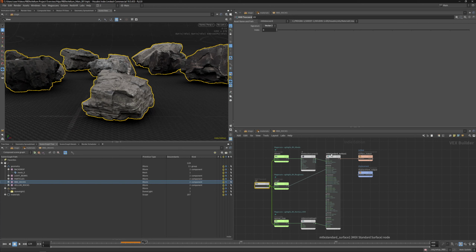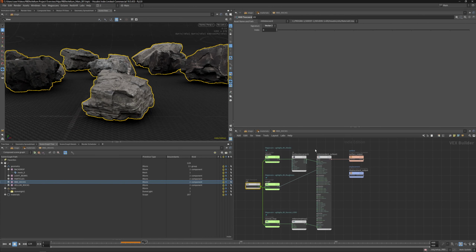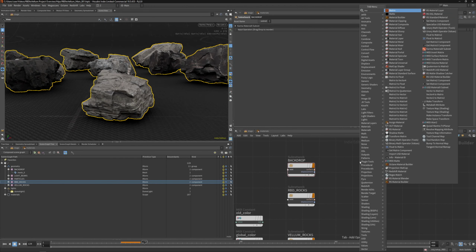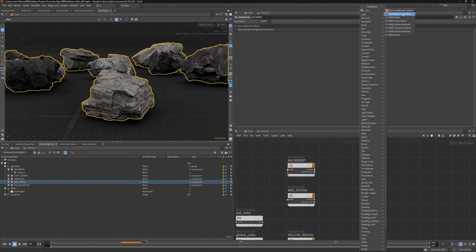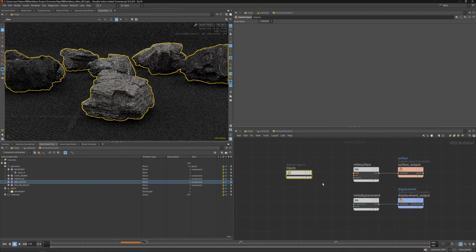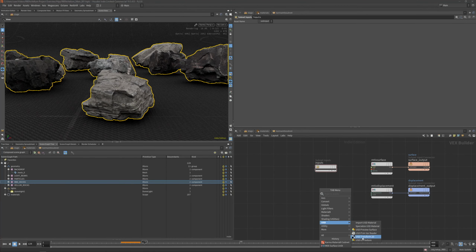And I should mention that for this project I'm using MaterialX. I mean, I always use MaterialX with Karma. And those subnetworks actually are Karma MaterialX subnetworks, not the MaterialX subnet. Not this one, but the Karma one. Because with Karma, you have some additional nodes, some additional USD nodes such as the USD UV texture and primvar reader. This is for importing your custom attributes.